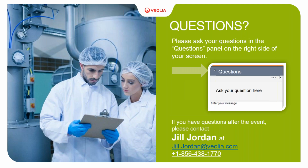And just last follow-up question about that. If a municipality has a granular-based system, would you still avoid seeding it in an industrial application? No, you could use it, but you have to be careful again that the municipal plant could have been treating sanitary sewage, which means that you may have to get special permitting to dispose of your sludge if your reactor is not treating sanitary sewage.